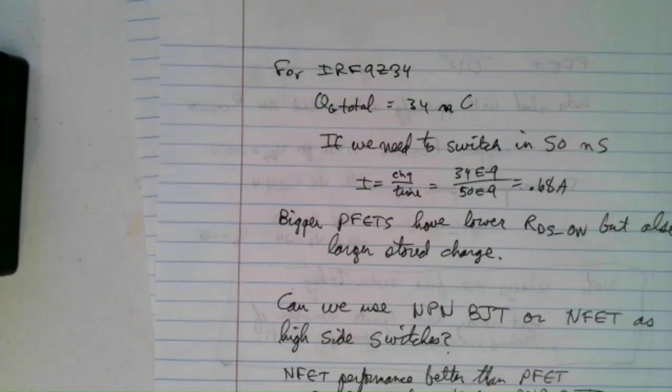And I would encourage you to be careful if you're working with big motors like that, because if you're having trouble with the run current, watch out for the start current, because the start current is liable to be 10 times the run current. Especially imagine that you have a situation where something's mechanically wrong and the shaft on the motor is locked and the motor can't run.